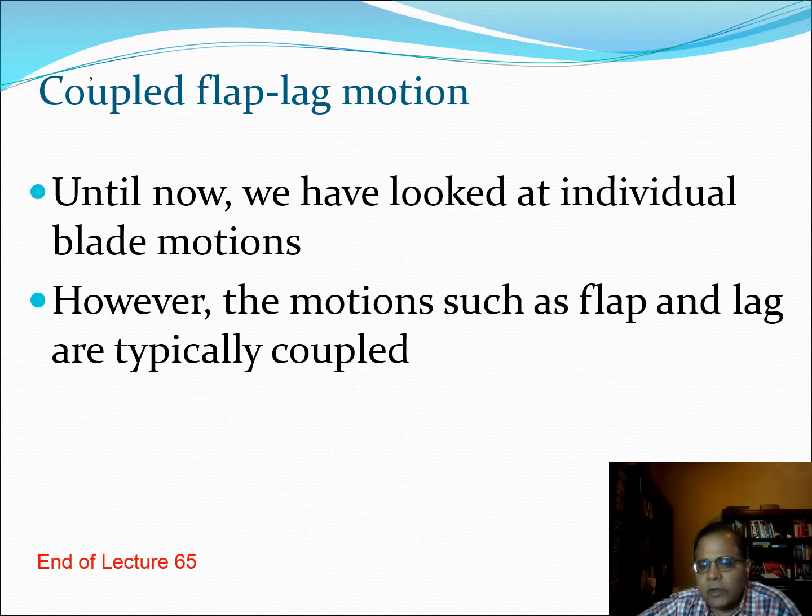So very often a favorite question of people is, why is this helicopter system so nonlinear? And sometimes people say it's because of large deflection and so on. Now, large deflection is of course true, but the helicopter system is nonlinear primarily because of the presence of these Coriolis terms, and it is not necessary that the system must have large deflections for these terms to be present.